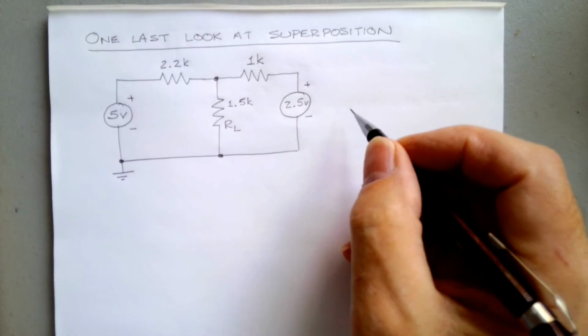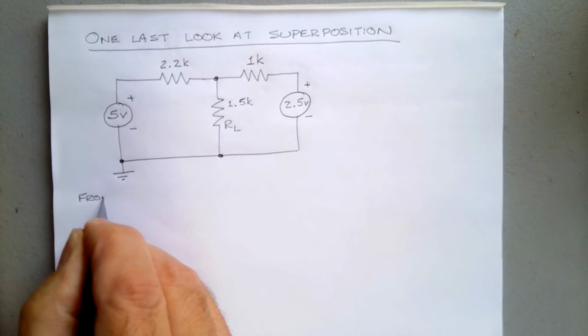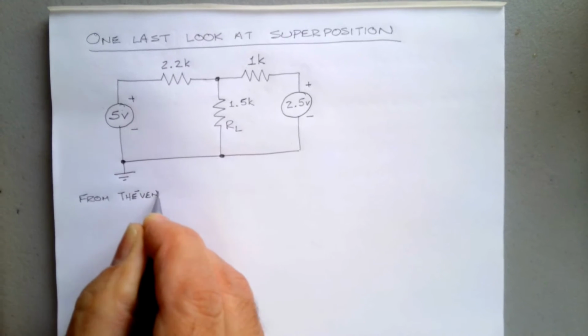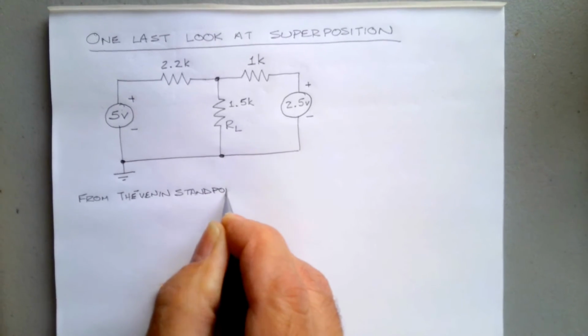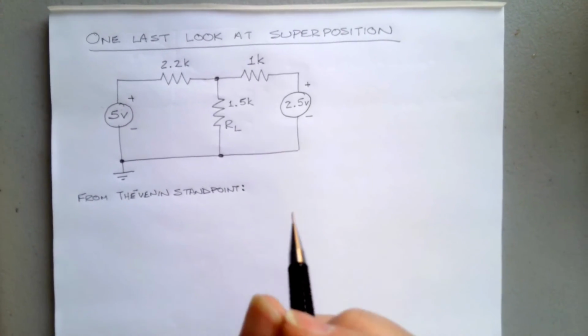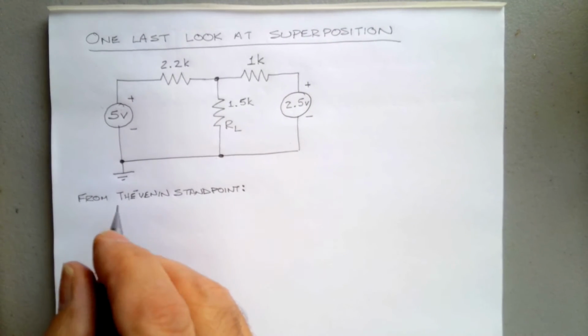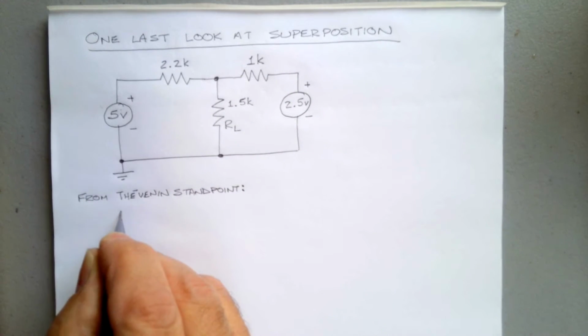So if we wanted to look at this from a Thevenin standpoint, we would remove the load, look back in, and deaden the power supply.